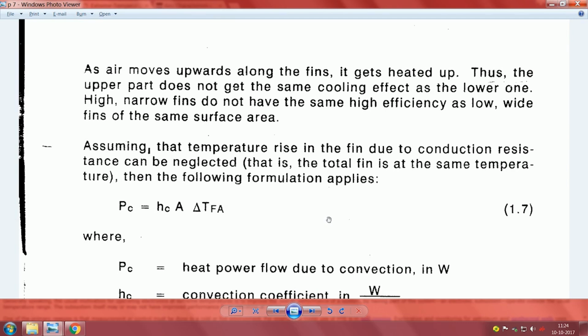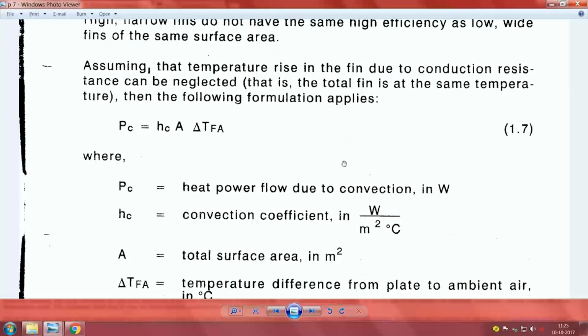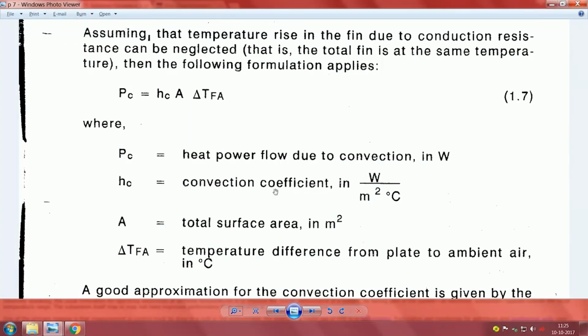So, if you put more and more fins, obviously more area is available, and then why not put grooves along the fins, which I told you in the case of a commercial thing, how to make the grooves. If you have to depend only on natural convection, it does help a little. In fact, probably it helps a lot. So, here for the purposes of completion, they have given how to determine this heat transfer coefficient.